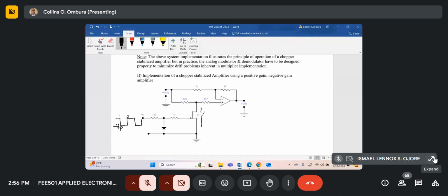So when our control voltage goes positive, it will be clamped by this diode. It can't go more than the forward bias of the diode. If you use a germanium diode, that will be approximately 0.1 volts, so the maximum positive it will go is about 0.1 volt. The maximum negative it can go with respect to the earth is minus Vp, which is the voltage required to turn the MOSFET off.